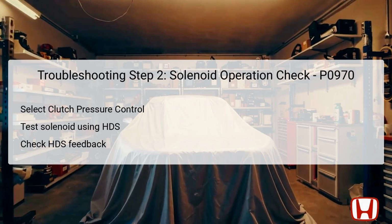If the HDS indicates that the solenoid operation is normal, this is a positive sign that the valve may be functioning correctly and that other factors may be causing the DTC. Conversely, if the HDS shows an abnormal response, further investigation into the solenoid and its wiring is warranted. Remember, a functional solenoid is crucial for proper clutch engagement during gear shifts.